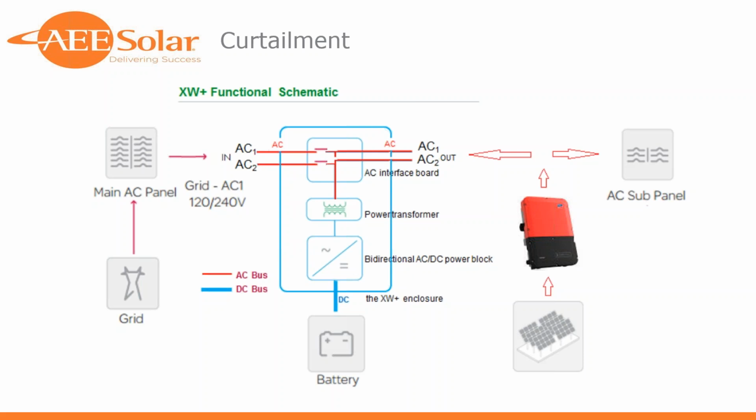The PV inverter, coming back to that, doesn't make those decisions. Again, it's trying to supply as much power as possible, which in a net metered environment, hey, that's great. This is energy that I'm not going to have to pay for later. The grid's willing to take it. I'm going to keep shoving power onto the grid. The problem can occur when we talk about UL 1741SA: if it sees that grid voltage or grid frequency start to rise, it's going to start to pull back and curtail power, which, from a smart grid point of view, is exactly what it wants to do.